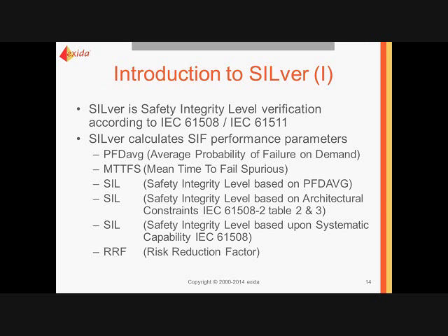It calculates the safety instrumented function performance parameters. We mentioned already PFD average for the average probability of failure on demand. It looks at mean time to fail spurious. This is something that is important to define and be able to comply with, and needs to be determined when you're doing your SIL determination, and you include that in the software requirements specification, the system requirements specification.